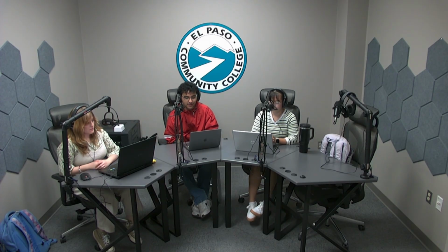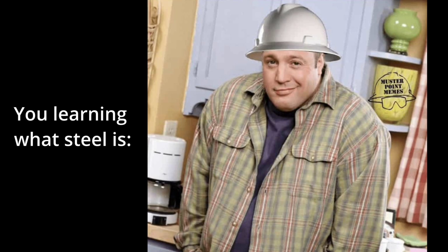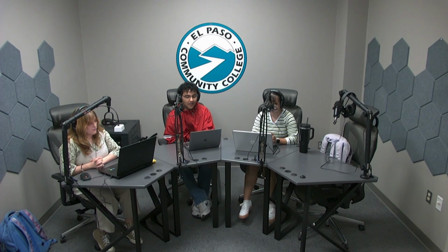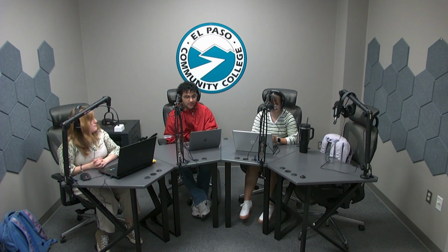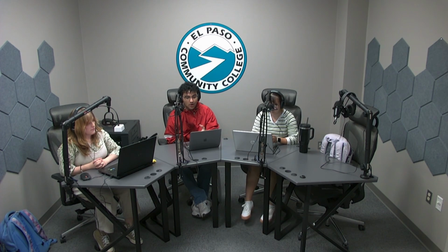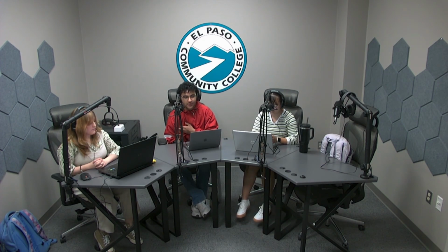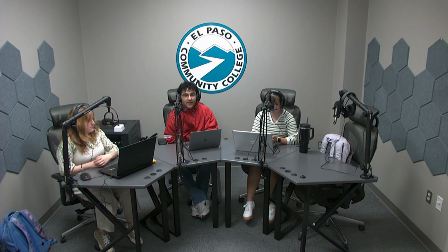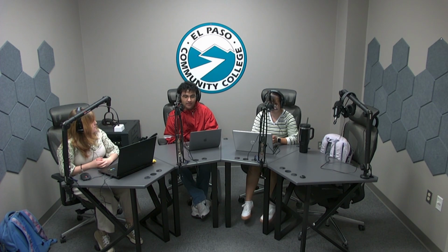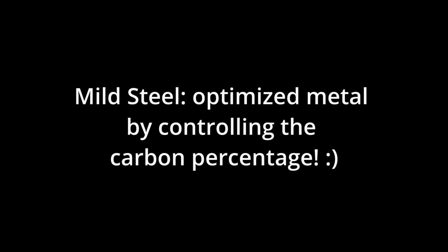So, what is steel? Steel is any of a range of alloys of iron, which is pretty much iron mixed with other substances, that contain less than roughly 2% carbon. Too much carbon makes a hard but brittle metal like cast iron, while too little carbon produces a malleable, weaker material like wrought iron. So mild steel is an iron alloy whose properties have been optimized for structural purposes by controlling these carbon amounts and other elements in the metal as well.